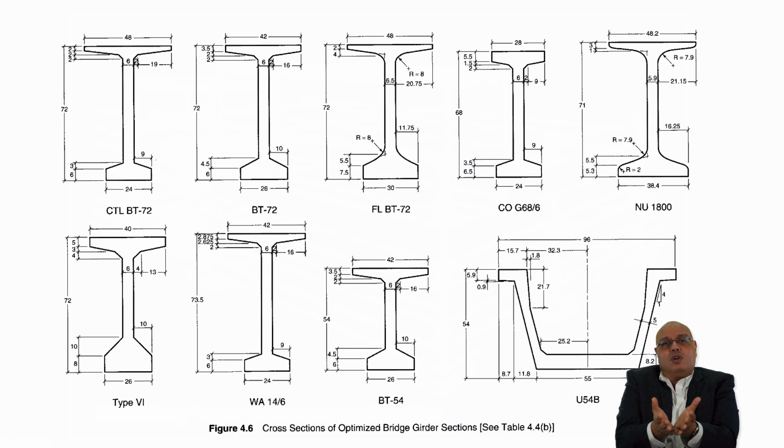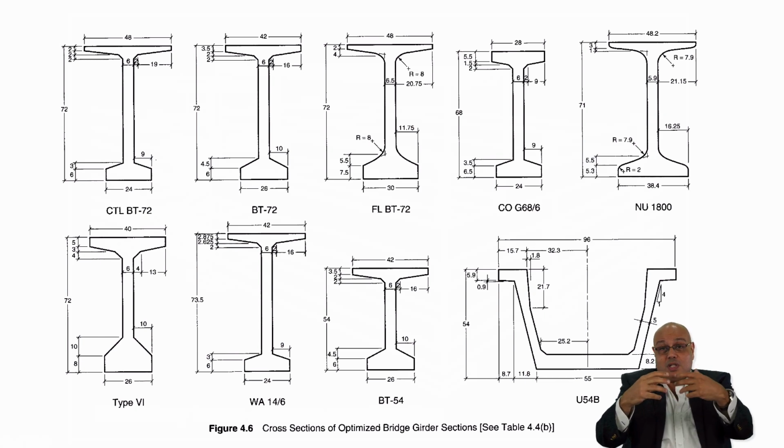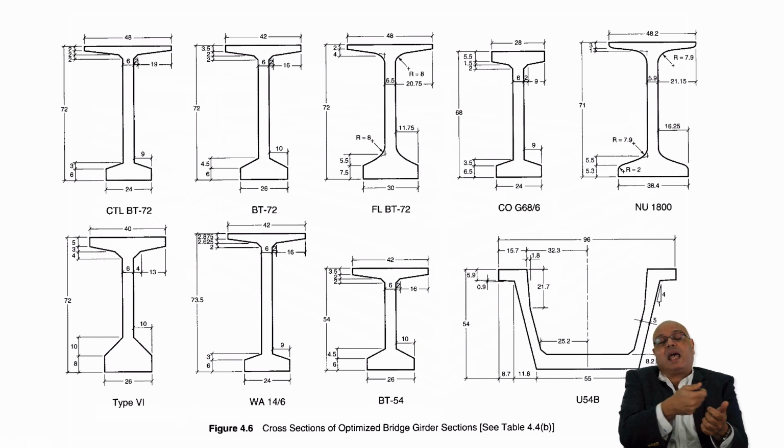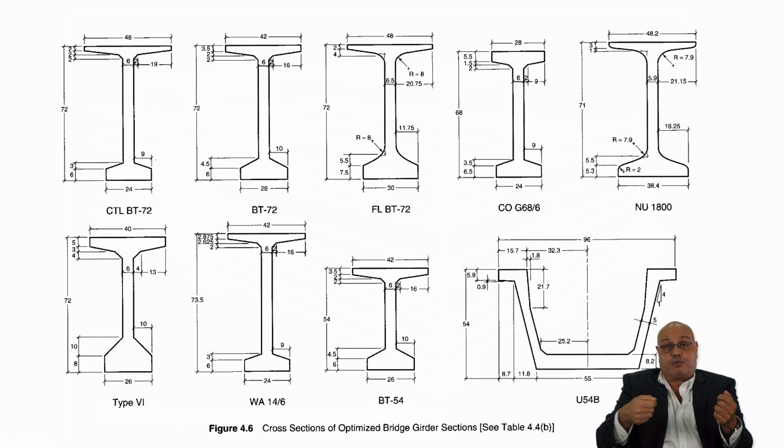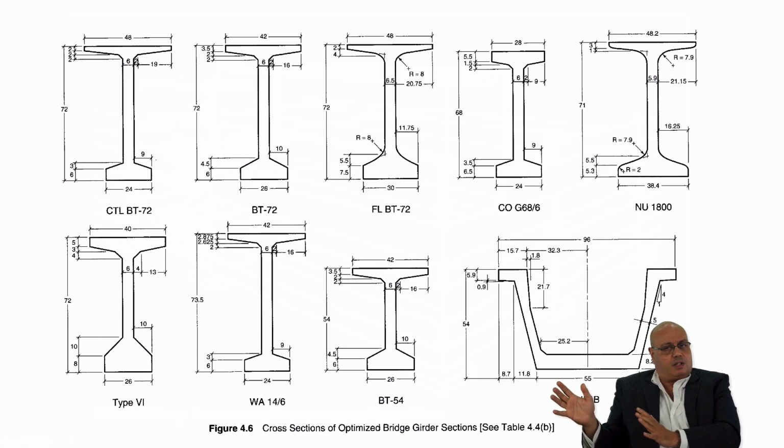It can only take 477 psi for 4,000 psi concrete, meaning that you need another material to capture this load and these stresses, arrest the cracking and close it, and this is nothing but the reinforcing steel that you have. We've known that in reinforced concrete.